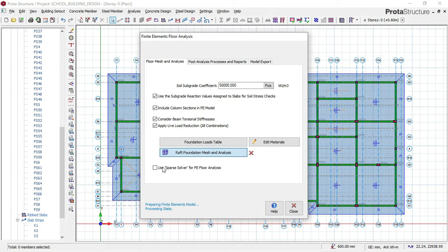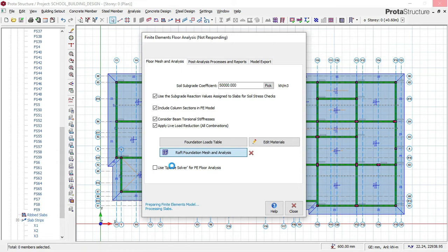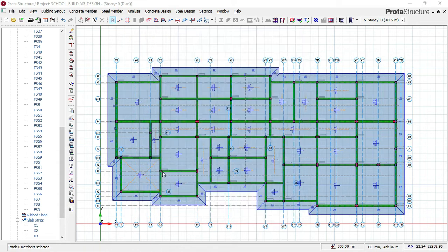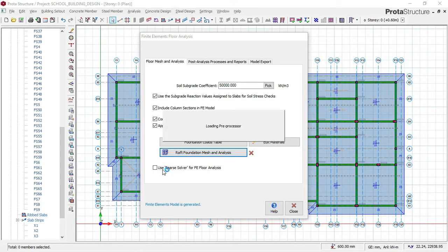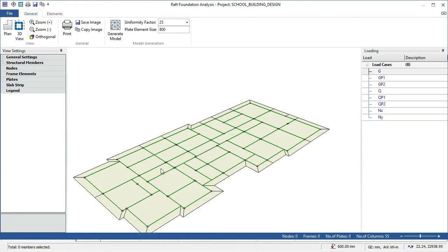Don't click on this space over, else you begin to have pauses in your design for the Raft Foundation. It begins to pause on each level. We mainly use this if you're designing for, let me say, a 10-story building, 15-story building, a high-rise building. Then we can use this, so that when it gets to that, it will be performing the floor analysis level by level.